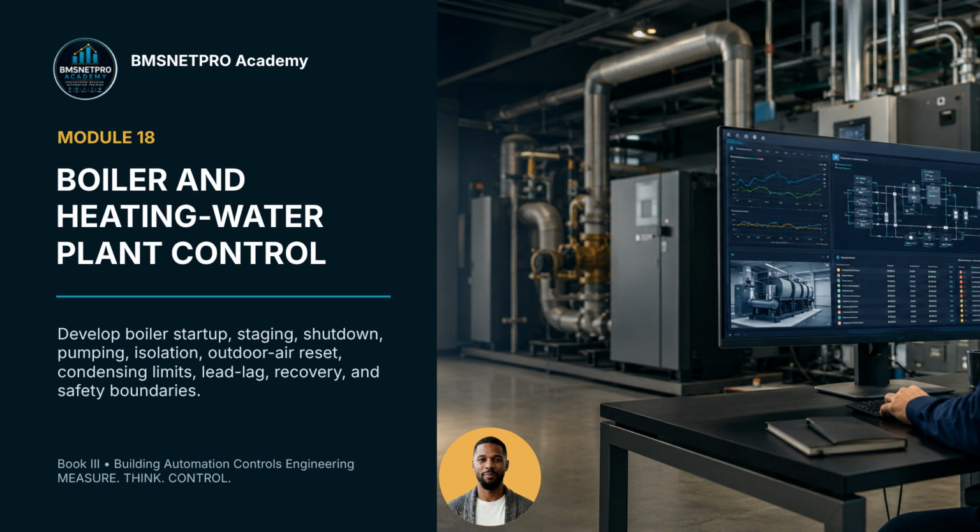Welcome to Module 18, Boiler and Heating Water Plant Control. In this module, we focus on how a BAS coordinates heating demand, pumps, valves, boiler enable, supply temperature reset, staging, shutdown, and recovery without crossing the safety boundary of the boiler or burner management system. Boiler control must maintain safe flow, stable temperature, combustion protection, and useful return water conditions before it pursues efficiency. The goal is a heating plant that is safe, reliable, efficient, and understandable to operators.